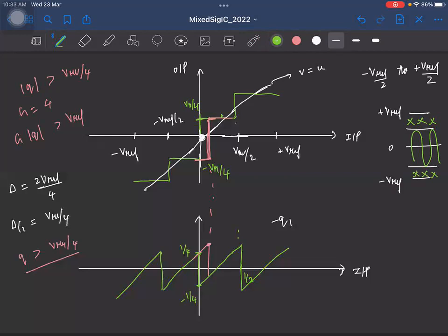That's what you are losing, these output codes. And that is in turn reflective of the fact that even though you have 5 bits, you don't have all 32 output codes, right? 5 bits can represent 32 output codes. But since you are losing these, you'll only have 16 possible output codes. Is that fine?